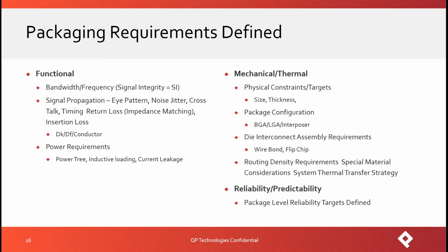One of the variations that does also come to mind is that we have in the past worked with very low CTE lead frames in some of our QFNs, which help for stability when that's a potential requirement. That is somewhat secondary to a CMOS camera, but might be important in various applications. Other questions?